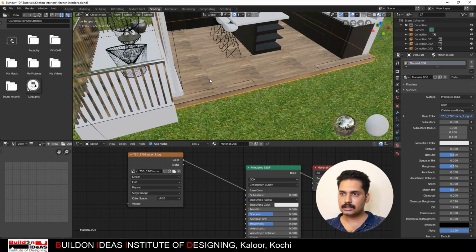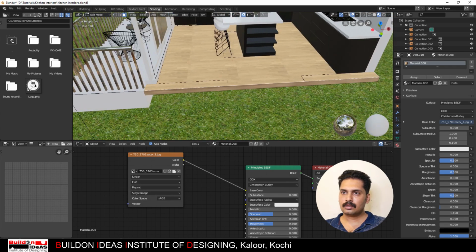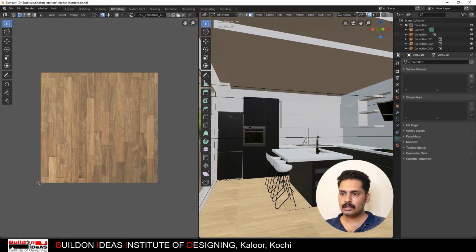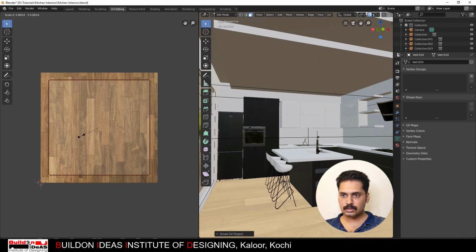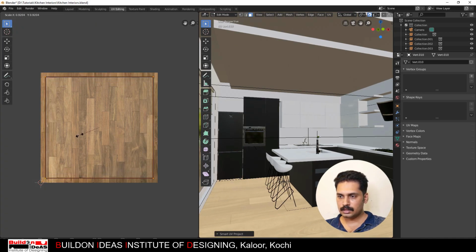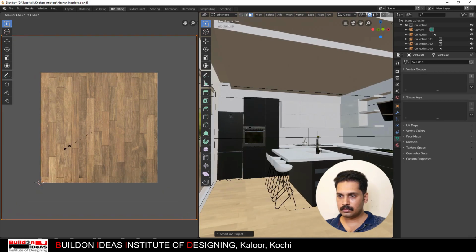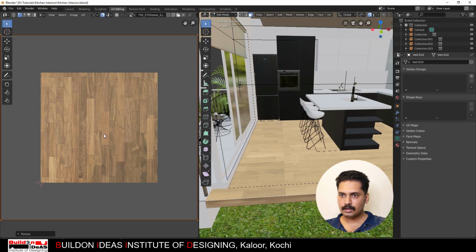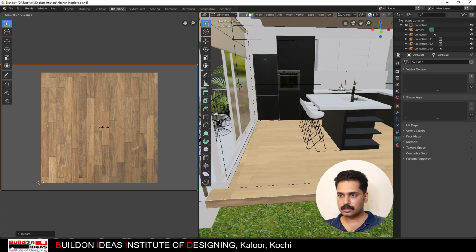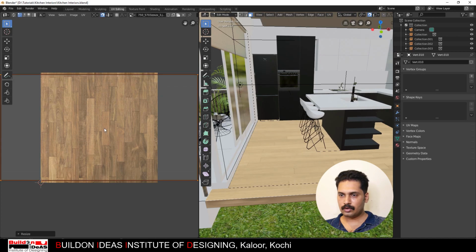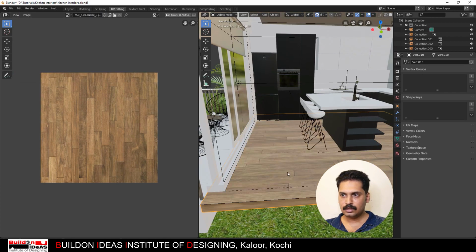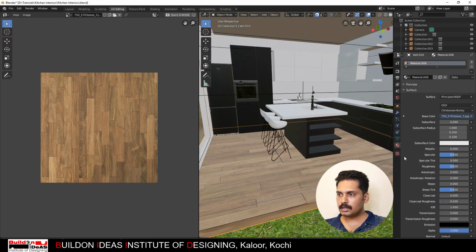What I'll do is I'll just select this face, and then coming to the UV editing mode, right click and then Smart UV Project. Click OK, and then you just give it a slice. Scaling, and in Y direction just scale it a bit so that not much of this is scaled. Okay, and now coming to the materials, just reduce the specular, increase the roughness,